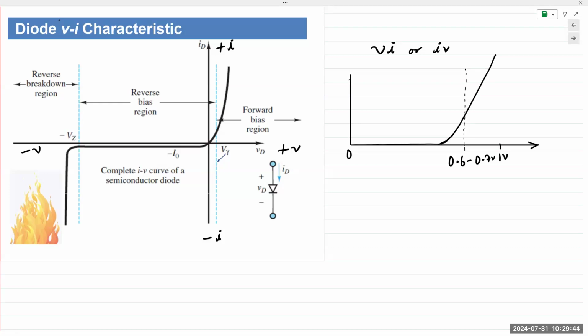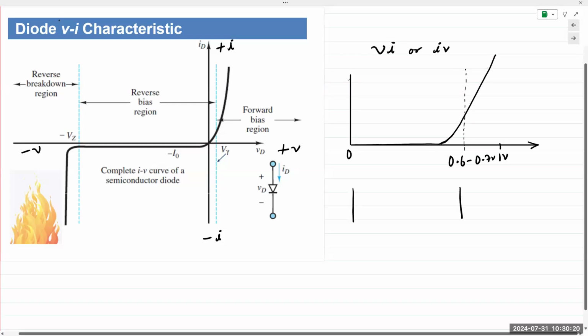It is so called because it is depleted of charge carriers. Because they're in close contact, electrons from the N side and holes from the P side will recombine. If they recombine, an electron jumps into the empty spot, thus removing one electron from the N side and one hole from the P-type material. So you have one less negative charge and one less positive charge, and when that happens, charge is gone. Up to here is your depletion region.